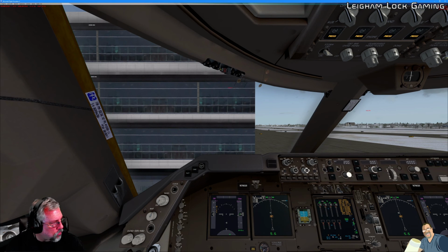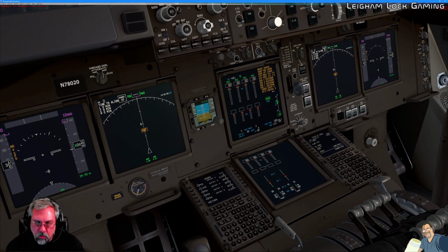So at this point, after looking at the overhead maintenance panel, we are ready to start programming our flight management computer. So we'll look down there, go to menu and back to our FMC, and here we want to confirm identification of the aircraft. So we are flying the 747-800. Our AIRAC data is current, so no change there, but we do need to initialize our inertial reference system with our current GPS position.